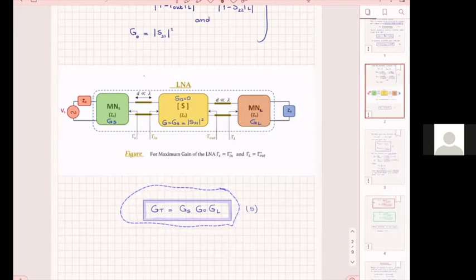It could be for that, but the most general definition of GT is the power that goes to the load under any matching conditions divided by the maximum available from the source. We use it everywhere. Obviously in the simple match, that's what's happening, but the definition applies to many other cases. It's a very meaningful gain practically. So it's given by this.